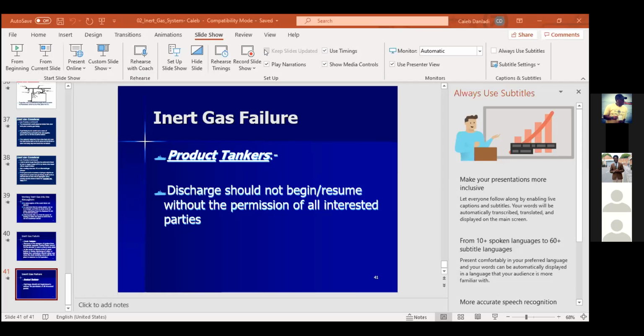And if you are 8,000 deadweight tonnage and carrying a low flash point cargo, then you must be inerted. I strongly recommend that you do not tell the examiner that you load a certain cargo with no real ullage level.